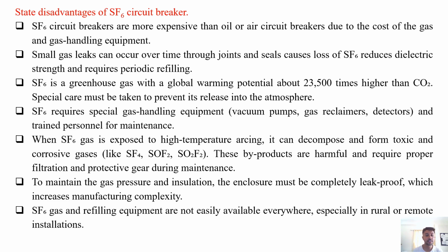Now, when SF6 gas is exposed to high temperature arcing, it can decompose and form toxic or corrosive gases like SF4, SOF2, SO2F2. These byproducts are harmful and require proper filtration and protective gear during maintenance.